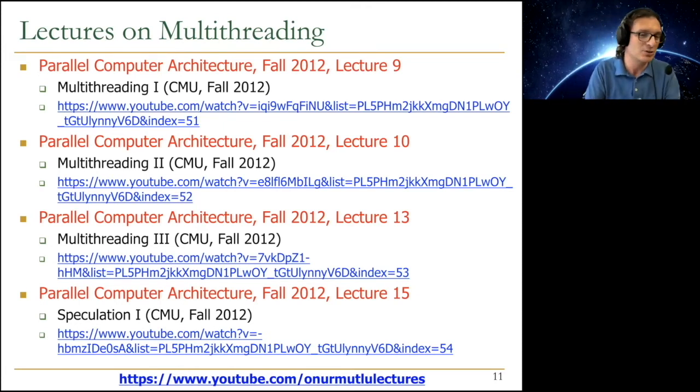Of course, you do redundant execution, so there are power concerns. But if one thread gets a fault, you can detect it, assuming the other thread doesn't get the exact same fault at the same time, right? So multi-threading has many, many use cases, as we have discussed, we have not discussed, but as these videos discuss. So if you're interested, there's a lot to think about over here. And multi-threading is a concept that's employed in essentially all modern microprocessors. GPUs employ a fine-grained multi-threaded version, for example. As we mentioned last time, Sun Niagara employs also fine-grained multi-thread version. Many existing Intel and AMD processors employ hyper-threading, for example, which is simultaneous multi-threading. And some other processors also employ a similar version.